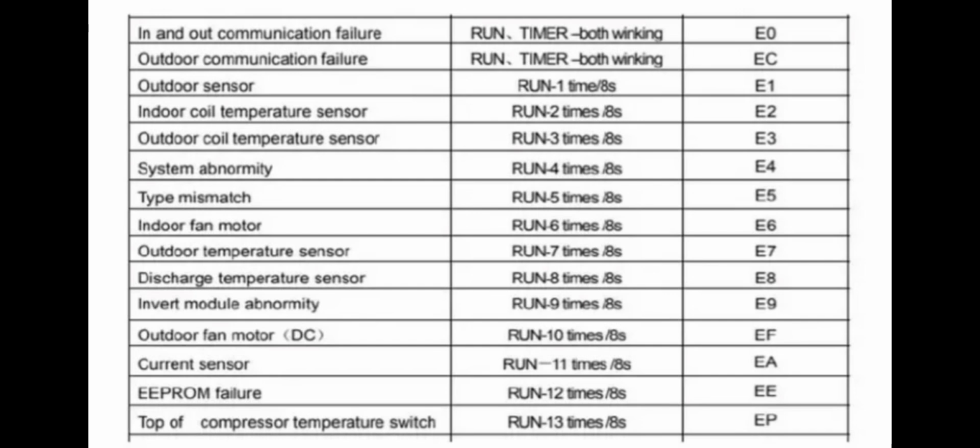And we have EP fault, which is temperature switch fault on the top of the compressor. Check if the wires of the compressor connect to the outdoor power source well, and if not, replace the outdoor power source board. You can replace the temperature switch as well.